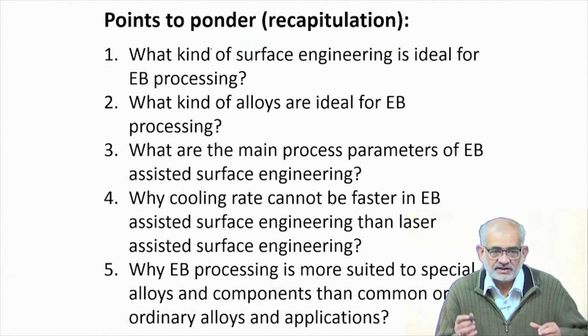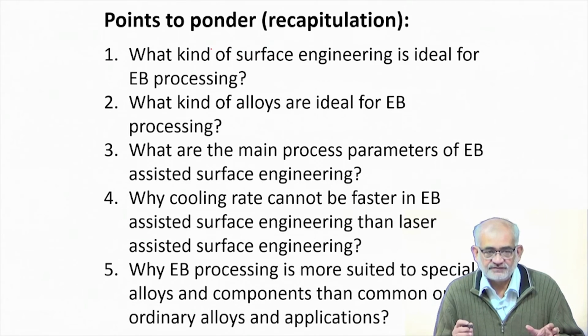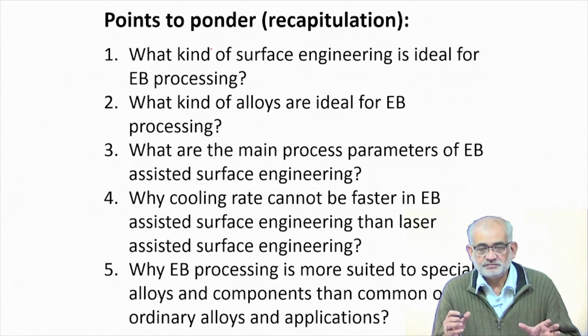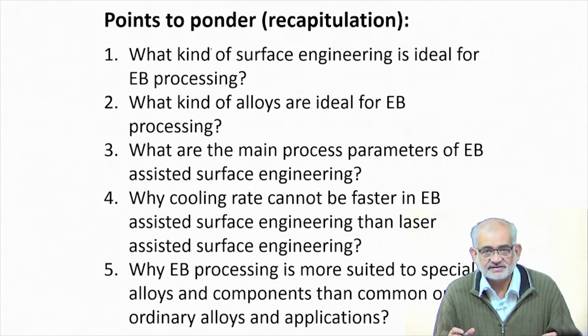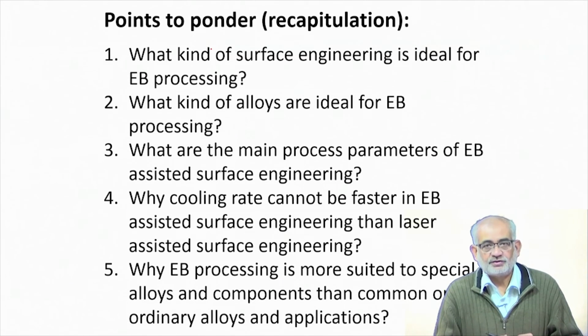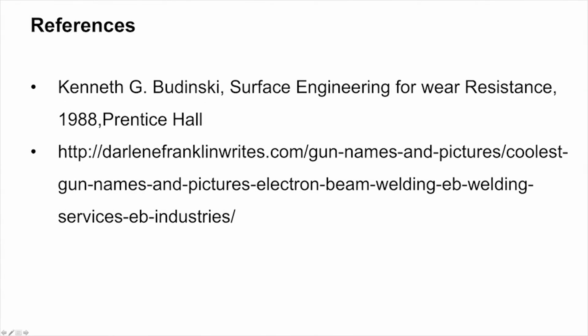But if you are dealing with sophisticated components which are expensive, the material is very expensive and at the same time very reactive, and you are not willing to take any chance, then of course electron beam facility will be most handy either for welding or for surface engineering. So thank you very much.